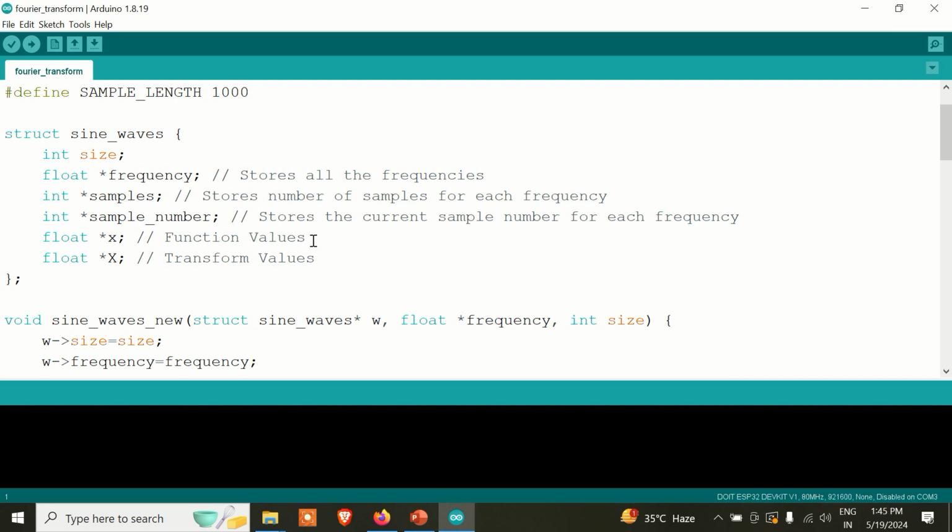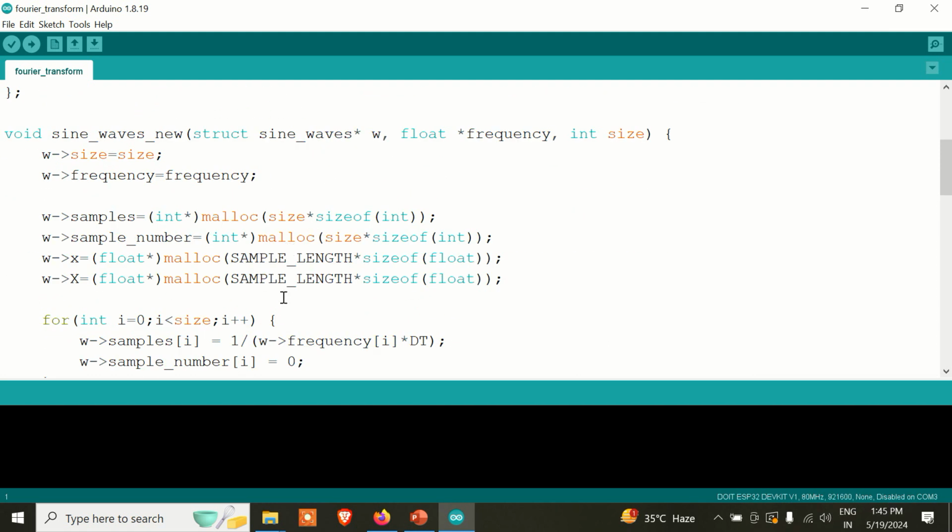So this program will convert your time domain signal into a frequency domain signal. Right? It will extract how many frequency components are there in the incoming signal. So how to implement a fast Fourier transform. FFT converts your time domain signal to the frequency domain and will give you which frequency component is contributing by how much value, so that the shape of the signal is made.